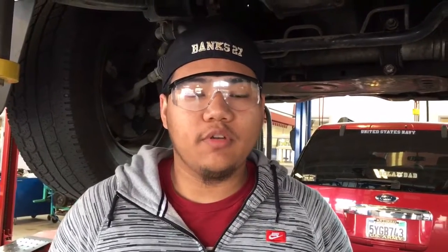Alright, today I'm going to be talking about the wideband oxygen sensor, the differences between the original oxygen sensor and a wideband oxygen sensor. So the main difference is basically the air to fuel ratio. A wideband oxygen sensor is more accurate compared to the oxygen sensor. The oxygen sensor only tests the leanness and richness around the 14.7 to 1 ratio. The wideband oxygen sensor tests all the way from as rich as 10 to 1 ratio to as lean as 23 to 1 ratio.